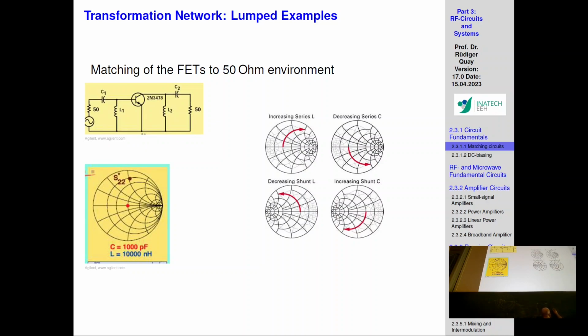It goes like that, and then through an air bridge it goes into the other conductor. So you have one conductor here, then a long meandering microstrip line, because if I'm not making any mistakes, any microstrip line will have an inductive component, a resistive component, and a certain output and input C.